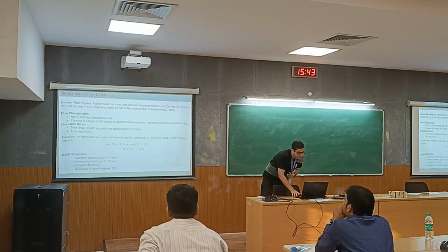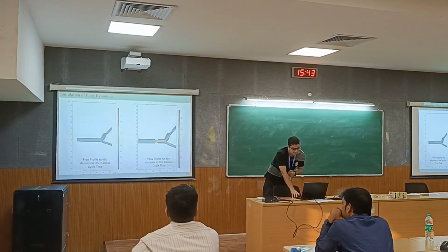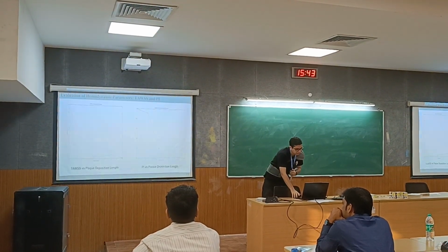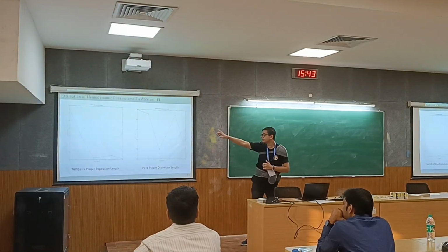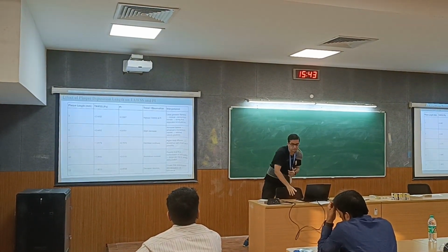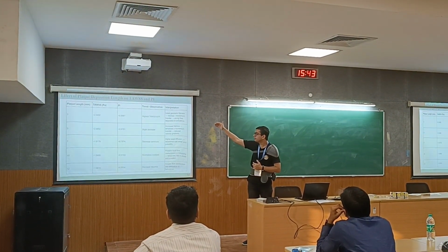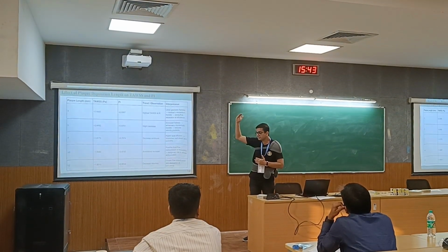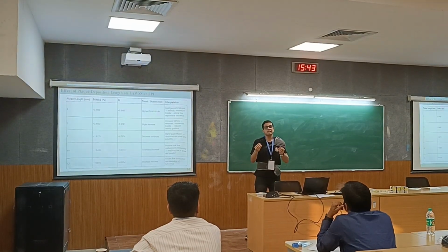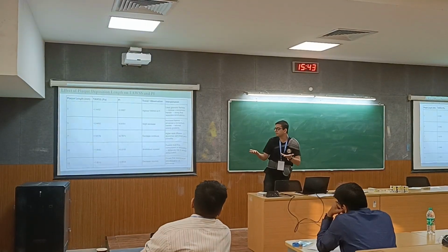Okay. Now we use laminar flow physics here, and this is the simulation. We took wall shear stress data, and from there we took the time average of the wall shear stress. This is how it was varying. This is how pulsatility was varying. Now, interestingly, what we saw was that the time average wall shear stress starts decreasing as the deposition length increases. This is because the curvature reduces and this flattens out, enhancing Z momentum transfer.